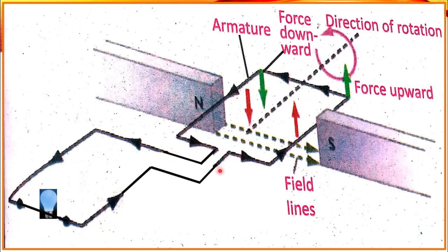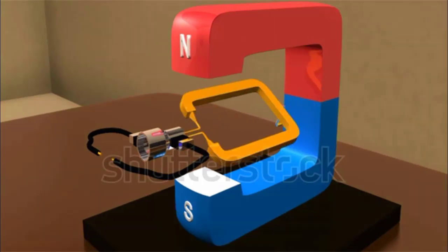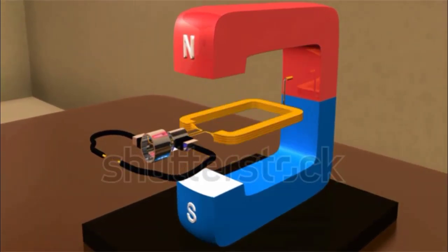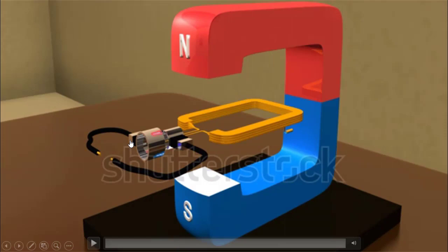Due to twisting of these wires, high potential wire comes in contact with the low potential wire, and a short circuit results, which can cause fire, which would burn the entire generator and the circuit would collapse. To avoid such kind of situations, we make special modifications in the circuit of the generator. We use slip rings and carbon brushes as shown in the figure, so that the coil keeps rotating inside the magnetic field without disturbing the external circuit. We shall be discussing their function afterwards.